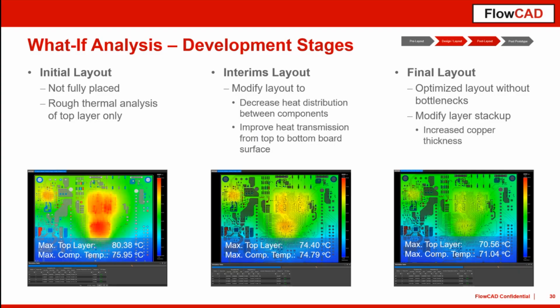And we can see, of course, in this case the pre-layout status. Let's say the devices are connected very, very closely to each other. Then we move them slightly away, because we also have to do some routing between these memory devices. And here we can directly see that the temperature relaxed slightly.